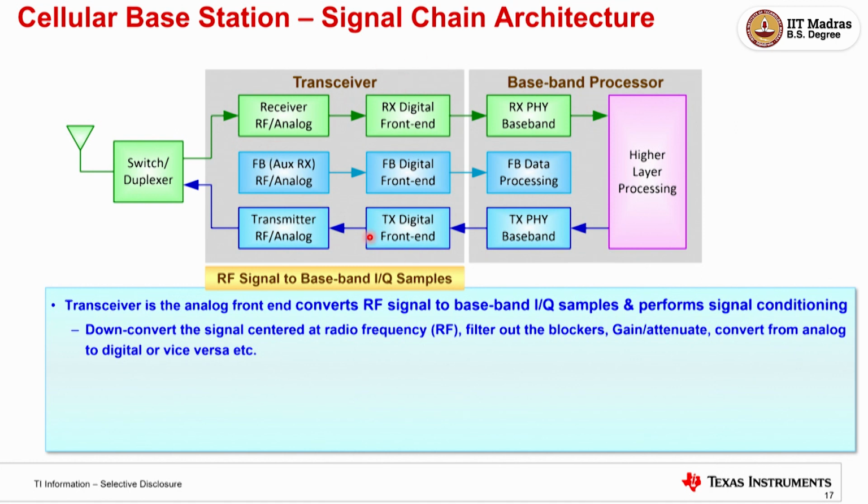But this is basically the analog front end, which converts the analog information into some form of raw digital information, which includes signal conditioning. We'll see what it is. It will include some gain, something in the curve. Finally, it will end with an analog to digital or a digital to analog converter. The boundary is where it is transformed to digital. That's it. But then the modulation part, how the symbol is mapped, the QAM and other things, are all done once it's all in bits. You do it in digital.